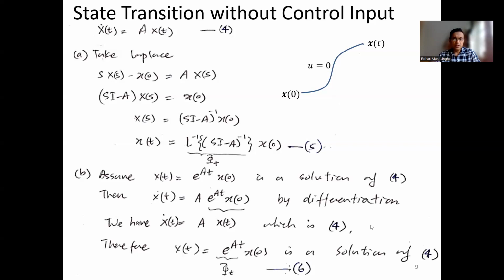The reason is the control signal controls the acceleration in order for the state variables to change. Usually, you do not have any control signal from outside connected to state variables directly. Any controls you have are connected to the rate of change of state variables. And if it's a single control signal, it goes to the rate of change of the highest state variable. So if you look at the position, velocity, acceleration thing, the highest state variable is velocity, and the control signal goes to the rate of change of that, which is acceleration, which is not a state variable.